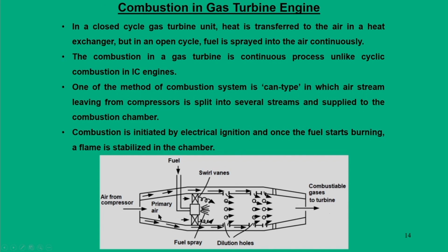But with time, this is a fuel rich zone because the entire fuel sees this air, and as the flame moves it gets additional air through the dilution holes. By this means the flame gets stabilized, so that we get a sustained flame throughout the combustion chamber. And when we have a sustained flame, we can ensure that combustion efficiency is very high, and all the fuel gets combusted.